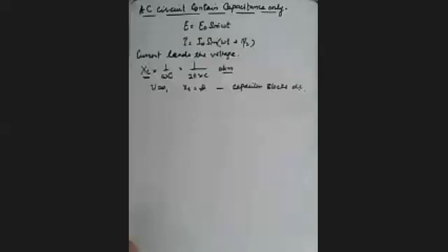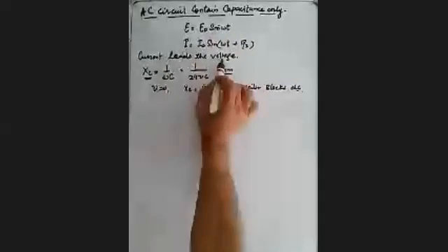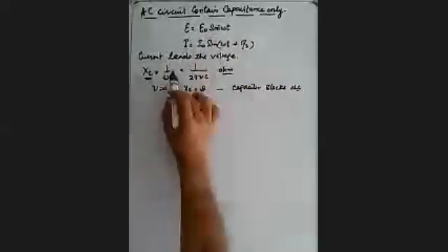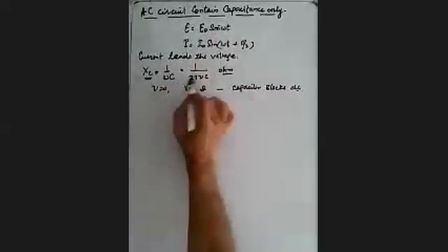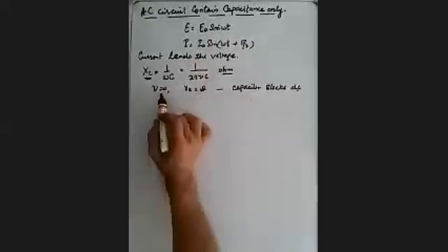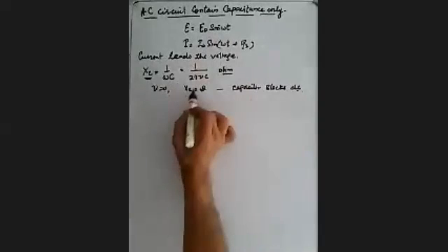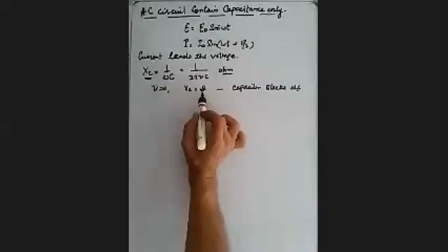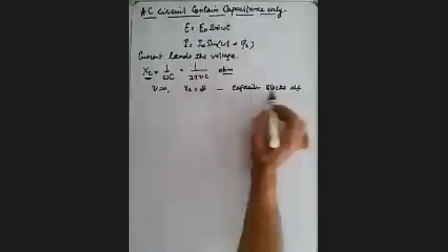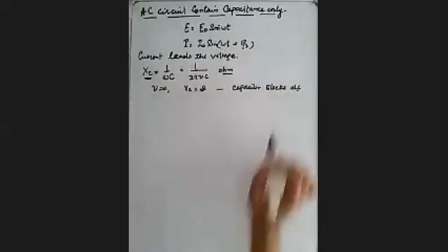by the capacitor. So that means in an AC circuit containing a capacitor, the current leads the voltage. Capacitive reactance is equal to 1 upon omega C, that is 1 upon 2 pi nu C, and the unit is ohm. So in case of DC, because frequency will be 0, XC from this expression is infinity. That means a capacitor blocks DC but allows alternating current to pass through.